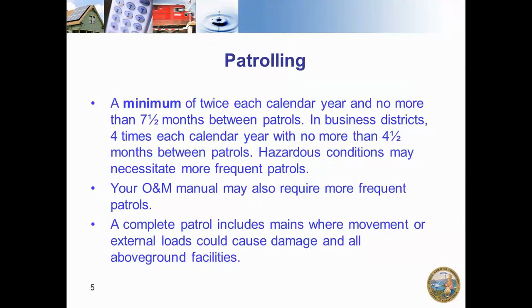And to go along with that, just going and doing your meter reads and looking at all of your meters is not necessarily a sufficient patrol. You need to make sure that you go to the master meter and you take a look at that. If you have any other above ground piping in your system, then that should be examined as well. So make sure you're including all the required facilities.